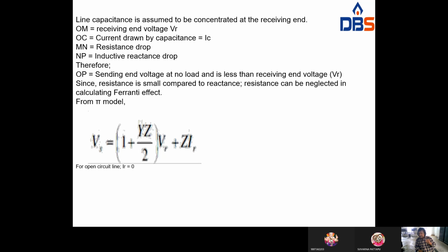Now, Ferranti effect is occurring at what load? Is it a light load, no load, or a full load? It is a light load or no load. At no load condition, what is the current? No load is nothing but open circuited. If the load is open circuited, what is the current? Receiving end current Ir is 0. If the circuit is open, current does not flow, so Ir is 0. So substitute Ir equal to 0.